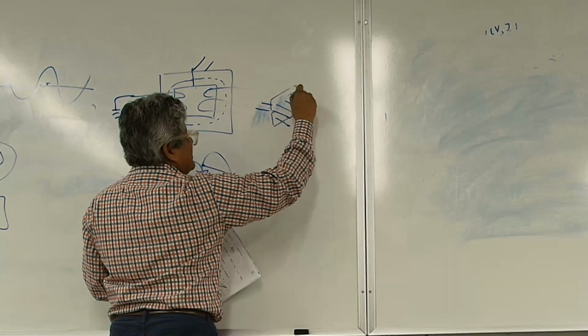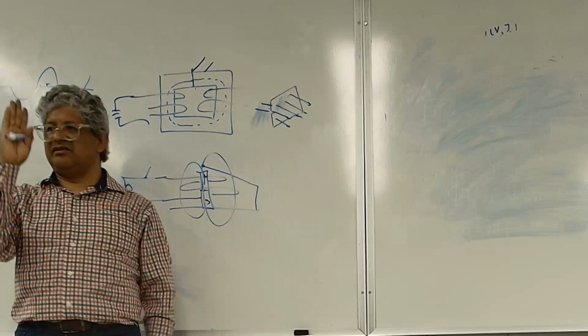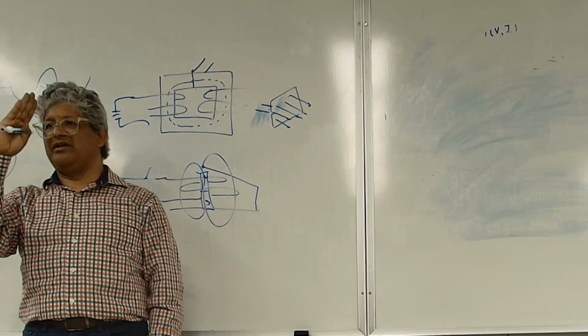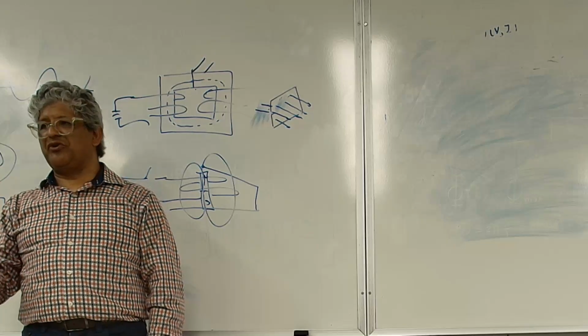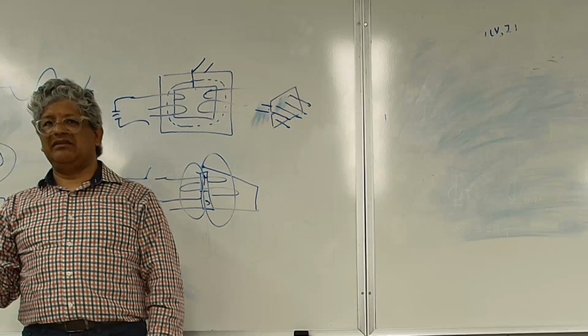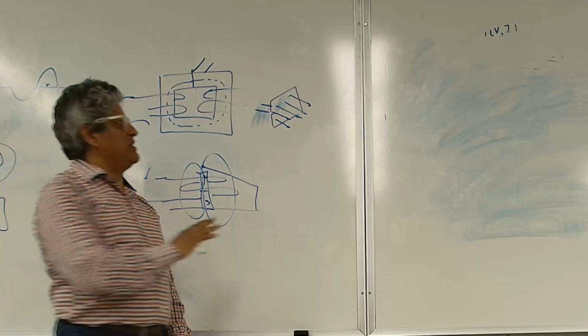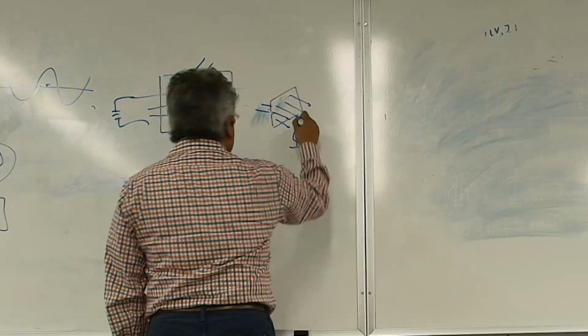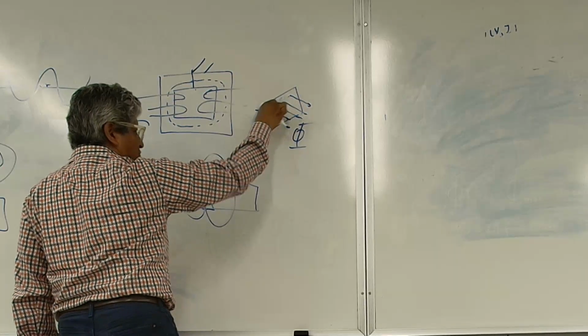Remember we talked about this? And I said the area must be perpendicular. How can I change the flux density? If I change the angle of the surface area, that's one. If I push more current, right? Remember I said that? And if I have more turns, remember I talked about that? So that's the flux. That equation is talking about these little arrows. Obviously, we combine them into one.